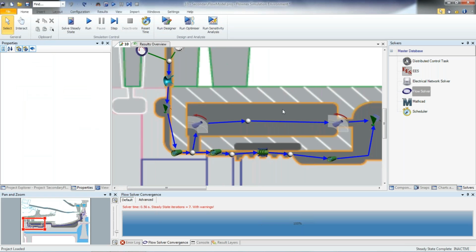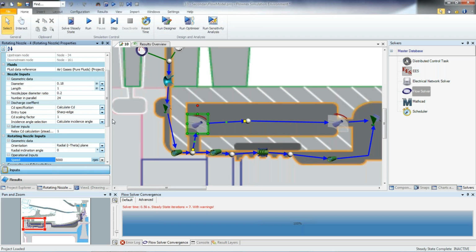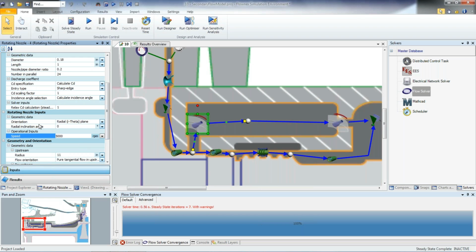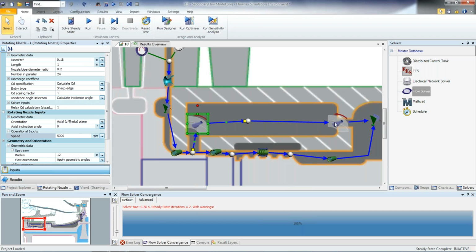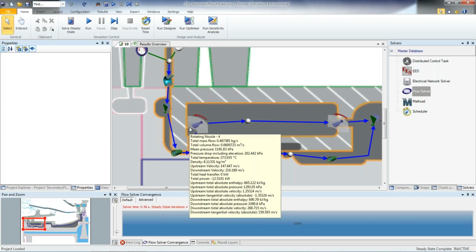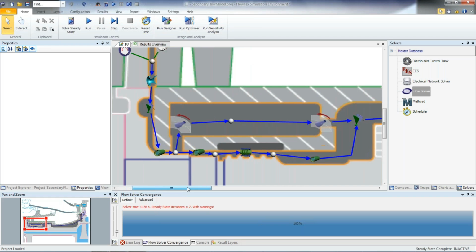We then have a cavity at the top here with nozzles at the inlet and outlet. These nozzles are modeled as sharp inlets. So the profile at the inlet is considered sharp here. We then specify the diameter and the length of these nozzles and the orientation of the nozzle itself. So in this case over here we have a radial nozzle and on the right an axial nozzle. All of this information is used in calculating the discharge coefficient and the effective pressure drop over that component when used in calculating the airflow distribution between these branching paths in our network.